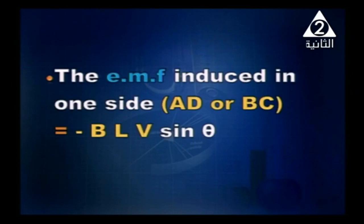The EMF induced in one side, and we've managed to obtain this before, is given by the expression minus BLV sine theta. B is the magnetic flux density, L is the length of the side of the coil, V is its linear velocity, and theta I explained.